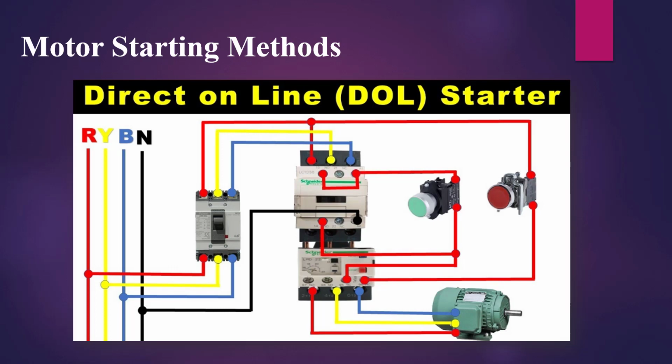The starting equipment consists of a main contactor, effectively an on or off switch which is suitable for the required current, and a thermal or electronic overload relay. The disadvantage of a direct online starter is the high inrush current that occurs when the motor starts turning. It may draw a current that is 5 to 7 times the nominal current until it is up to full speed. These inrush currents can generate mechanical shocks that warrant oversized wiring and additional surge protection.